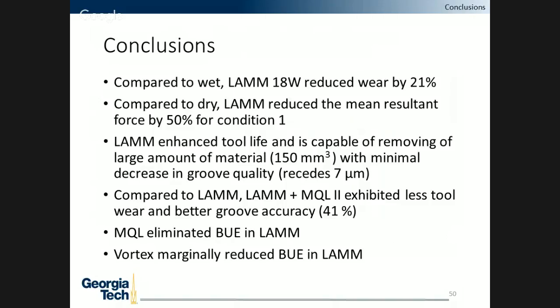So the overall conclusions of experiments 1, 2, and 3 are that LAMB was more beneficial than wet assist and greatly reduced tool wear, by 21% on average over many different cutting conditions. LAMB greatly reduced cutting forces, by 50% for some cutting conditions.